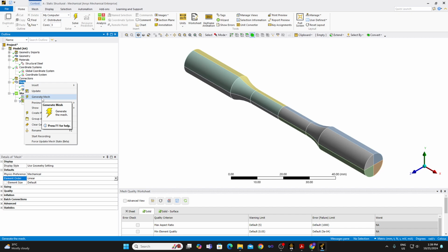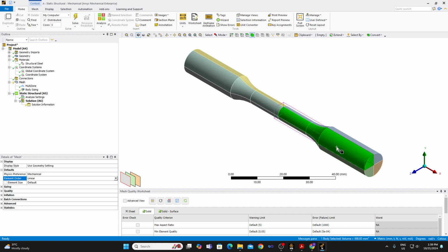Multi-zone is supposed to be a smart sweep method, where the software figures out what the sweep methods are. There are different sweep directions. One is the obvious sweep direction, the axial direction. The other sweep direction is where you take a given quadrant. There are 8 quadrants, so you can take a given quadrant, and the sweeping is done along the angular direction, from one plane to another plane.